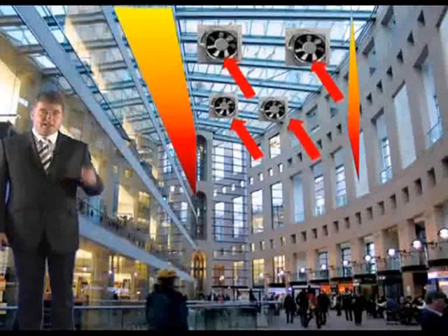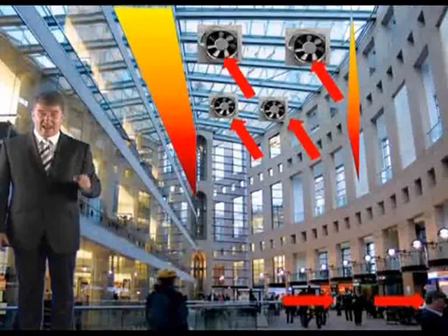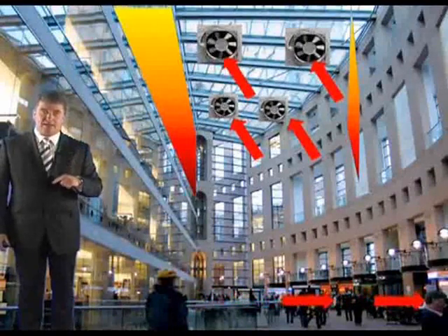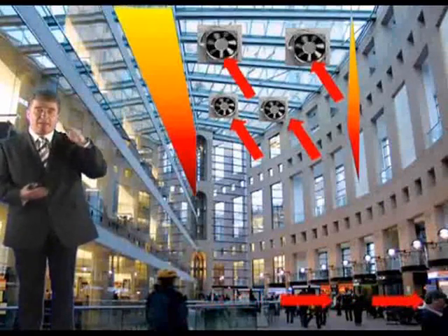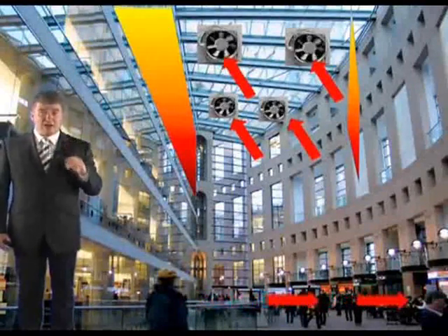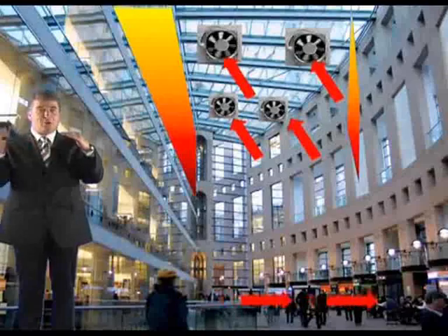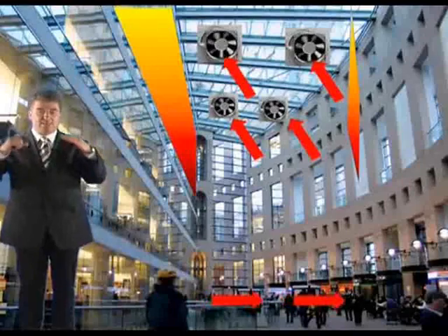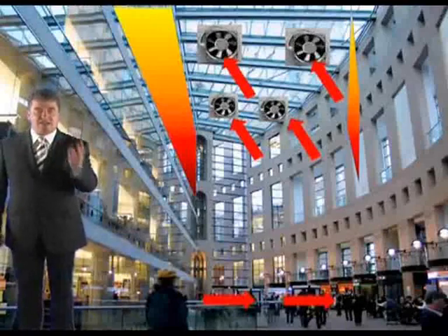And thirdly, since the gas is being extracted, and basically all of it is air mixed with a bit of smoke, fresh air must enter the mall to take its place. In other words, it must enter at a rate equal to what's been taken out, because if not, you get a back pressure. It must enter at a rate equal to the rate of extraction of smoke and at a low enough height not to mix. So there's no point having your air entry above the equilibrium height, because it's going to draw in smoke. The air's going to come into where the smoke is. It's going to make it even worse. So it needs to be lower than the equilibrium height, well lower, and it must come in at the same rate. They are the three essential features.